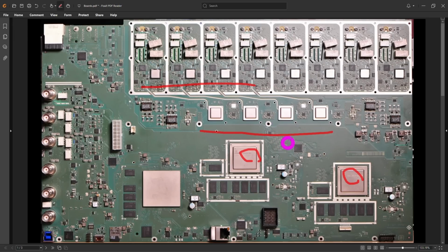There's another component over here which I could not really find the part number for, but I believe this is the PLL. There's a 100 megahertz crystal that feeds it, and this is likely providing the clocking required for these 4 ASICs and synchronizing them with the other PLL on the board. Now this PLL for the ADCs is pretty critical. We are dealing with 10 effective number of bits at a high sample rate, so you have to have very good jitter in order to even be able to accomplish that, and that's all coordinated, of course, among these different components.